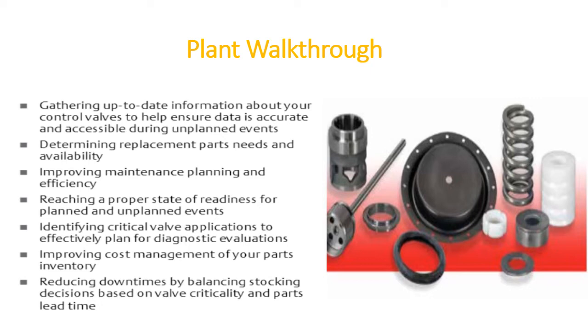So if you have 10 valves of the same type, you buy around 30% to 40% spare. And for the hard parts, you define the criticality of the valve. If the valve is very critical, or if the valve is in severe service, or if there is a history of damage of hard parts, then you buy the hard parts of only that type of valves.